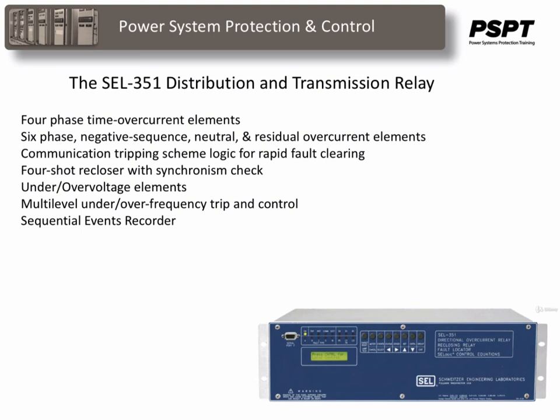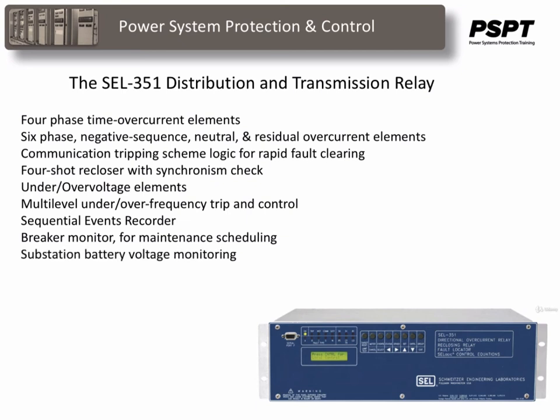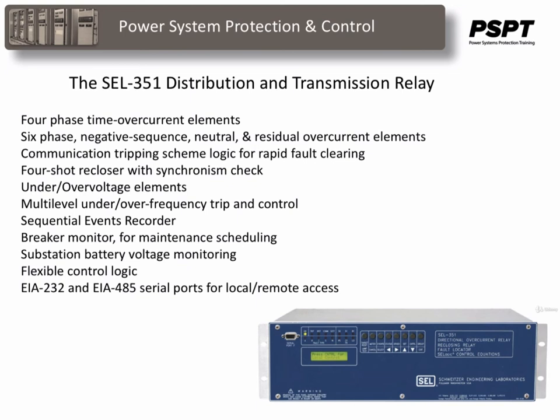It has event recorders. It records events and stores them and will release them on interrogation. It does breaker monitoring, which uses the breaker manufacturer's published data for maintenance scheduling. It has substation battery monitoring. It has flexible logic for traditional panel switches and latches and indicating lights. It also has EIA 232 and EIA 485 serial ports for local and remote access.